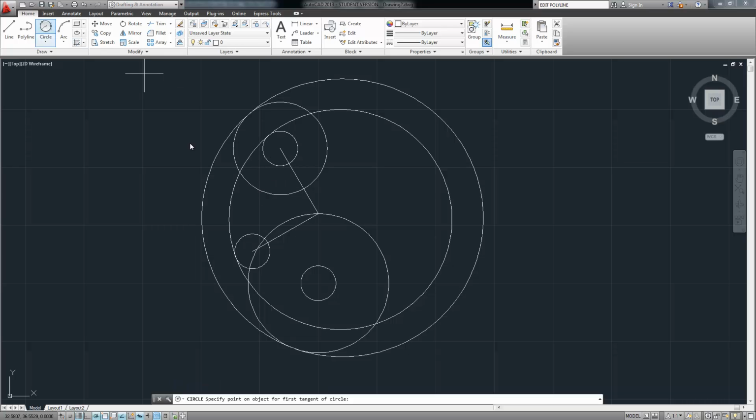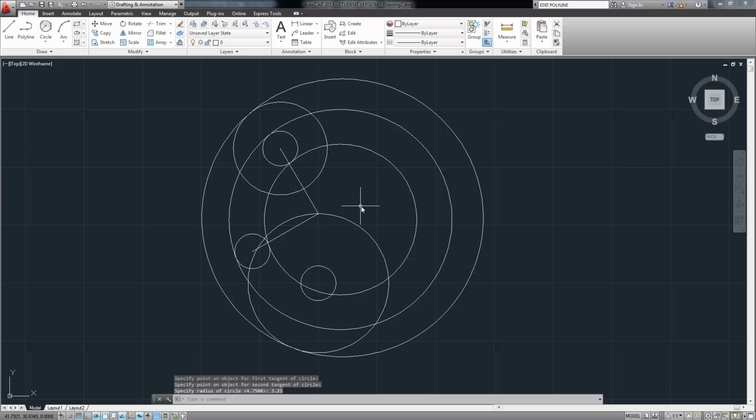Okay, and again for the other wall, select these 2 tangents, and that's going to be a radius of 4 minus 0.75, which would be 3.25. There we go. And then there is a fillet between this circle and this circle with a radius of 1. So let's select our fillet command. Now instead of selecting the objects, let's first enter our radius for the fillet command. And our radius will be 1. And then we select, there we go.